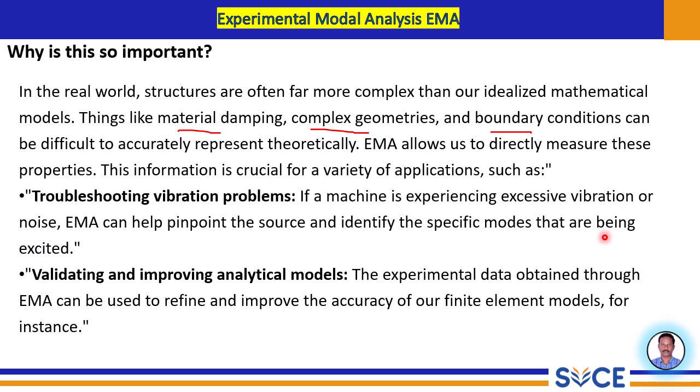Experimental modal analysis provides a systematic way to diagnose the root cause, that is, pinpointing the source, by identifying the specific natural frequencies that are being excited during operation and visualizing the corresponding modes or mode shapes. We can predict how the machine is actually deforming. So engineers can pinpoint the source of the problem.